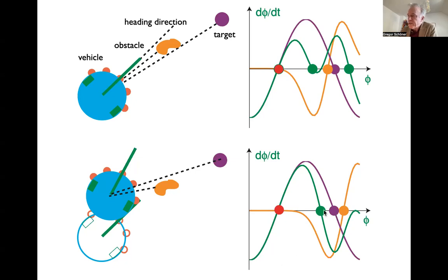And what the attractor does is that the solution of the dynamical system that will be handed down to the motors tracks the attractor. So it is not exactly sitting in the attractor because there will always be some delay depending on the time scale of the dynamics, but you will always be following the attractor, so be close within a certain limit of precision, close enough to the attractor. So in other words, you get this flexible behavior, and therefore you're sensitive to the bifurcations because you're tracking the attractors, and the attractors move.